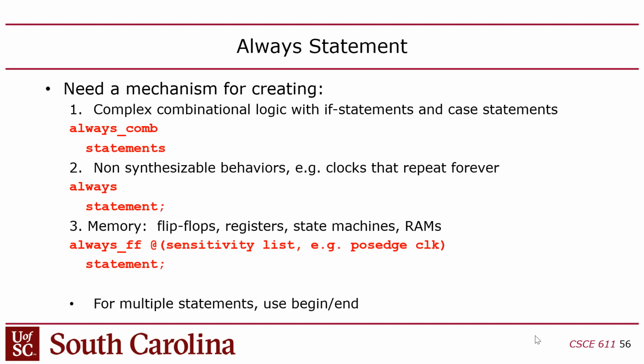Not a flip-flop, but a latch. It's going to end up being level sensitive, right? Unless, of course, you say posedge in front of C and posedge in front of D, in which case now it's a flip-flop. It's edge active. It'll activate on the rising edge of C and D. Then now I've made a flip-flop, right? But if I take the posedge out, this is a latch, because C and D will act as the clock gate signal for F. Otherwise F can change and it won't activate this block.